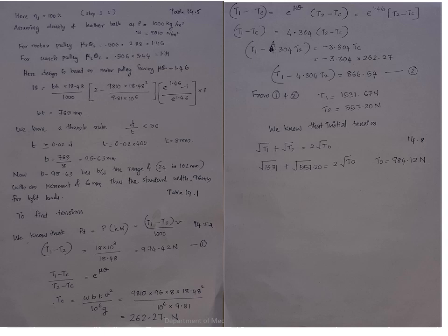For the motor pulley, mu s theta s is equal to 1.46. For the winch pulley, mu l theta l is equal to 1.7. Comparing these values, mu s theta s and mu l theta l, we will design based on the smaller value, 1.46. We will design for the motor pulley and substitute that value. We have 18 is equal to bt into a known expression. Then we obtain bt is equal to 765.